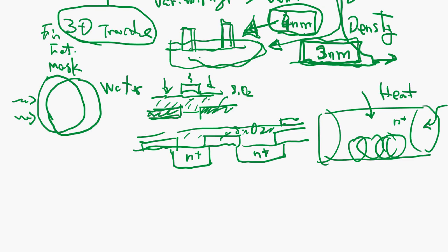Again, the place you want to leave the photoresist is going to be here for the gate. So the mask is going to be here. Let's see. You want to leave here, so you have to make an opening for photoresist, and fill with the photoresist.